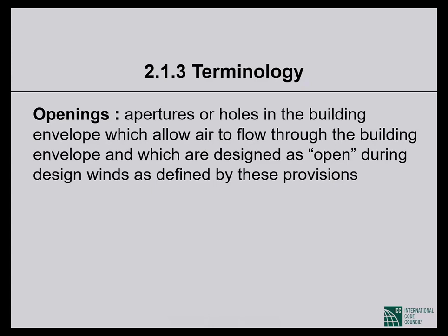If you have a roll down door, you still have to design considering it as an opening unless you have a crew in place and instructions in place, making sure that the roll down door will in fact be closed at the approach of a storm. If you don't have those things in place, then you have to take that roll down door as an opening. So that's kind of important.